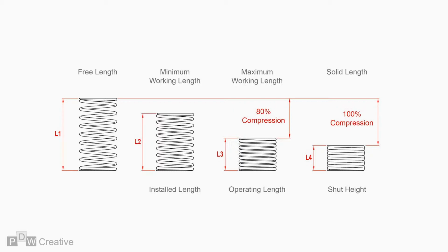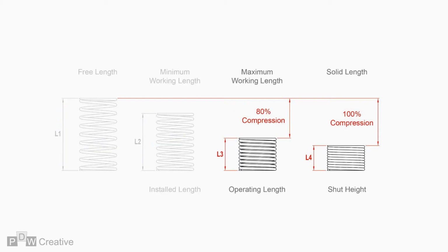When we consider stress, we need to look into the worst case scenario load cases, and this is because the spring will fail unless it can withstand this degree of loading. So we need to focus on the max and solid lengths here.